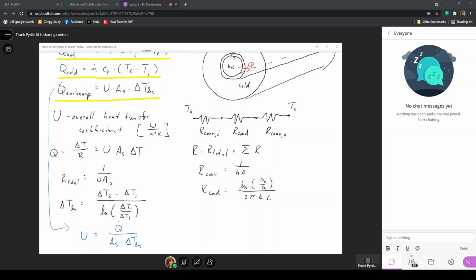11-1 are actually derived. As you set the two fluids with their known specific heats, you measure the temperatures and the surface area that is exposed on the inside and the outside, where heat exchange is going to occur out of the hot fluid and into the cold fluid. And you can calculate exactly what this value of the overall heat transfer coefficient is to establish those ranges.